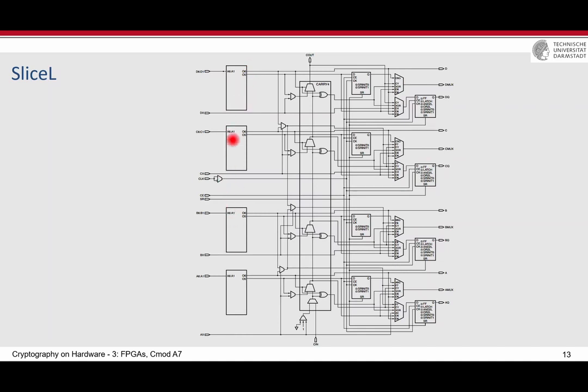And 4 of them here, you see there are some inputs for 6 input, 6 input, and 6 input, completely individually and different. And then 2 outputs are coming here, and here there is a register and clock enable, and here another register and a couple of multiplexers, configurable to say whether the output of the LUT goes to the output, or whether the output goes to the register and the output of the register goes outside.